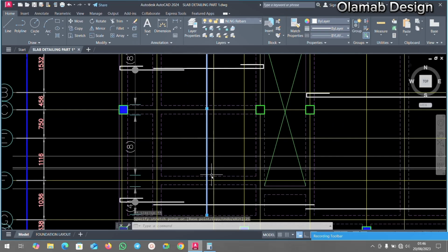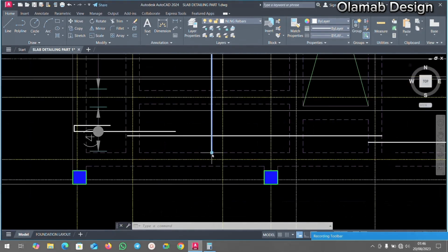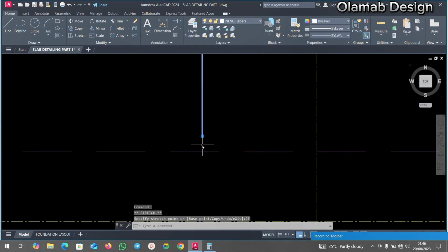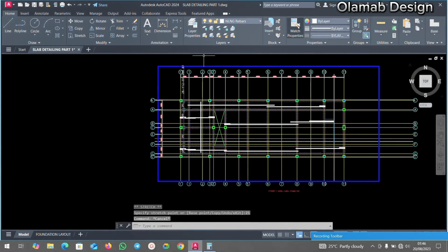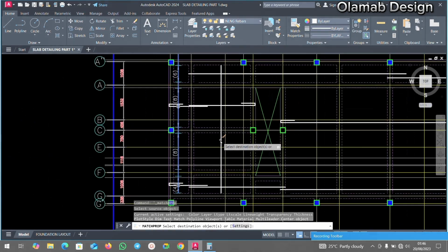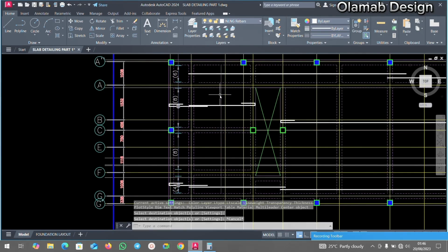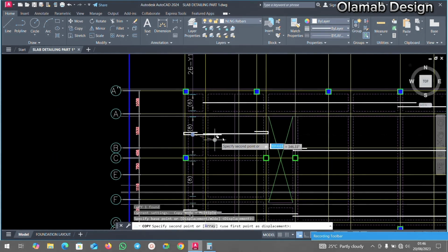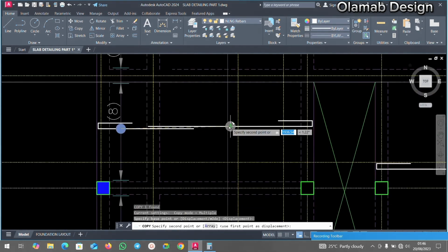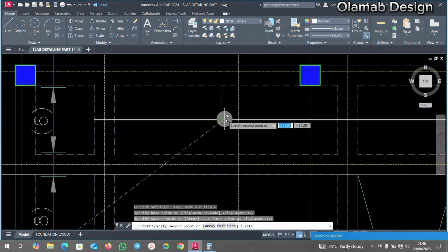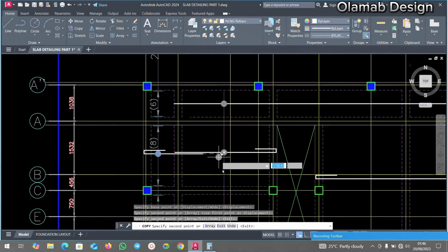Then here also I'm going to do the same thing at this place. So remove your cover, 25, I'll hit enter. Then I can just click on match property. Since this is the one I'm using, I will click on this. Then I'm also going to click on this particular one. Then I can pick my donut here, CP on my keyboard, hit enter, pick this right here, and place your donut on your rebar. Let's also place this on this one.